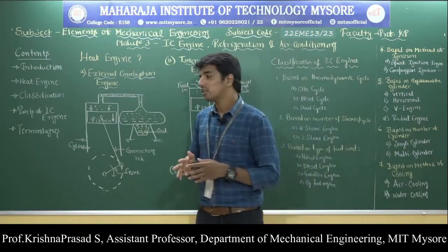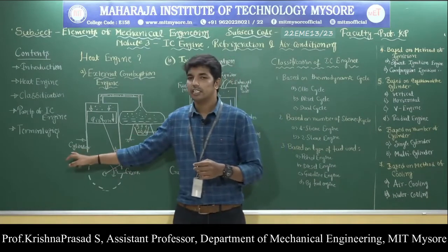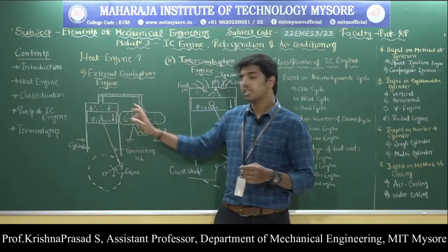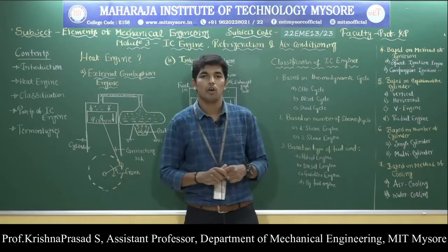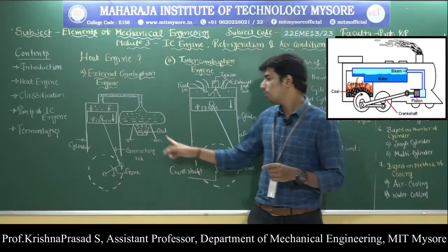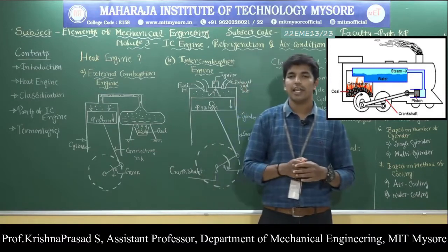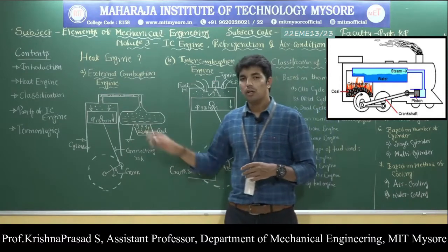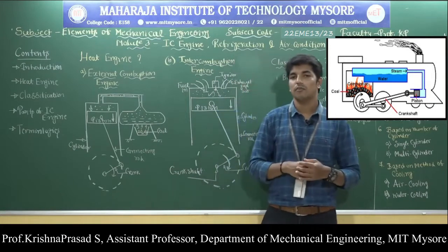combustion engine. So, what are the main parts of the internal combustion engine? Very important: the cylinder, piston, connecting rod, crank and the crankshaft. Okay. So, observe here, in case of the external combustion engine, the combustion of the fuel takes place outside the engine cylinder, and coal or steam generated from the boiling of water is mainly used as a fuel.